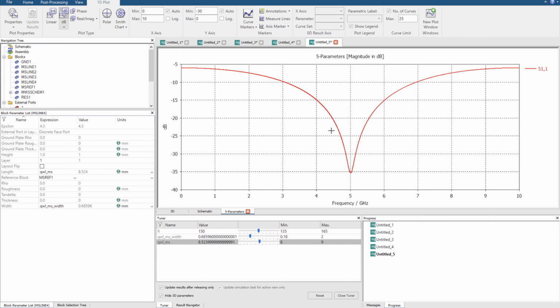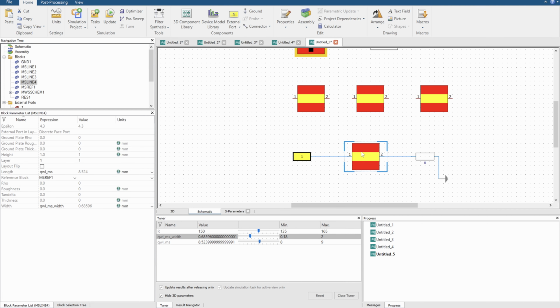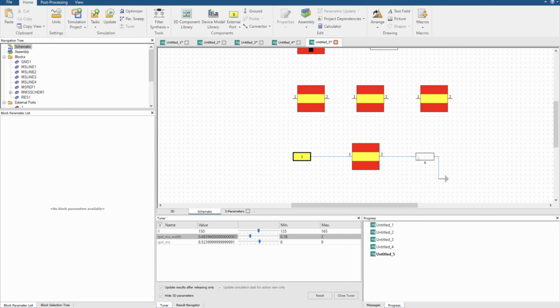Now, I can then calculate what that impedance was, because I just created 0.7, so I could reverse engineer what the impedance is of this line here. I know I started with 50. If I know I had a line of, let's say, 50 here, and then, I don't know, I got something like an impedance of 100, I could then calculate what the input impedance is of this block here, or if I had an unknown network. So that's another powerful tool.